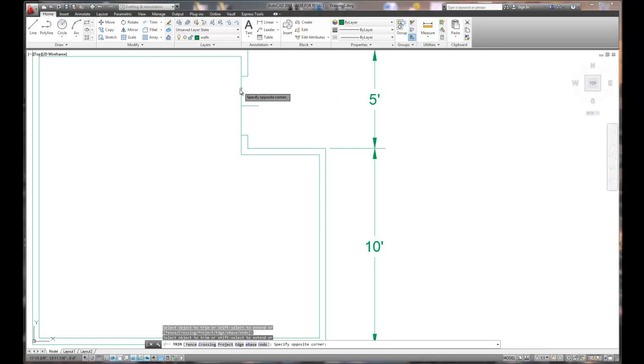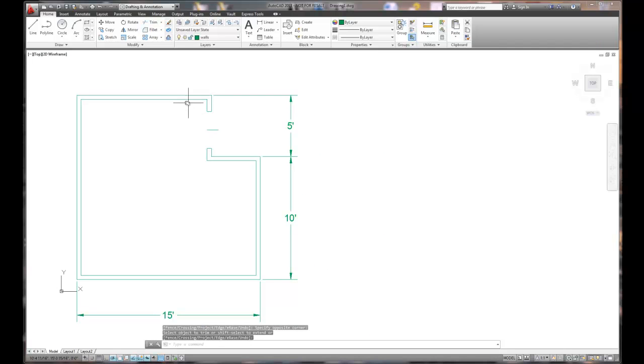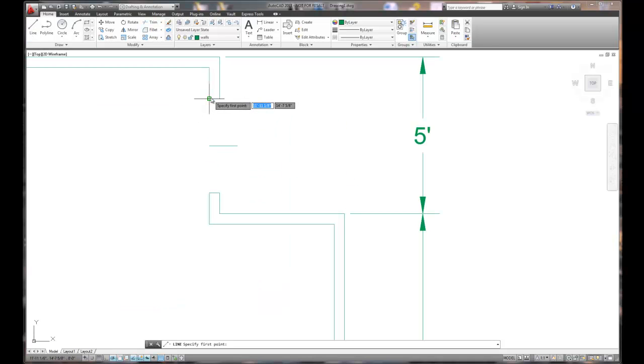And then we'll clean up the doorway. Okay, now doors typically have a door swing, and we're going to have the door swing in, because most entry doors have a 3-foot, or excuse me, a door that swings in. So the hinges are going to be located here. We'll swing the door in, and so I want to set an angle, and we'll put a radius in also.